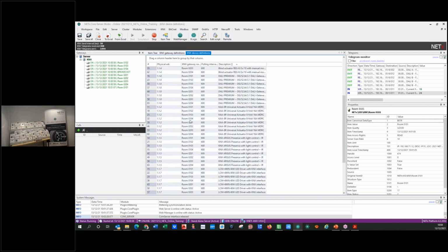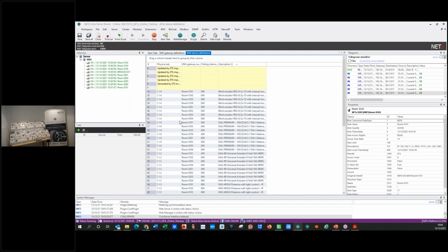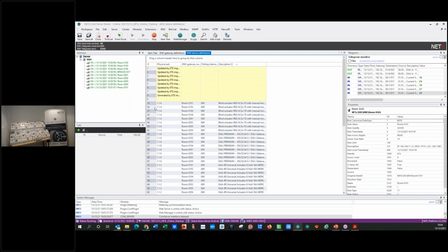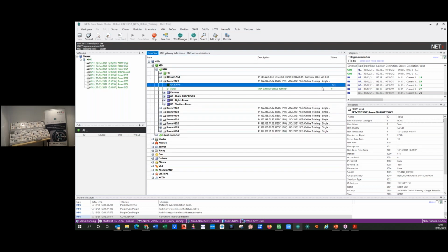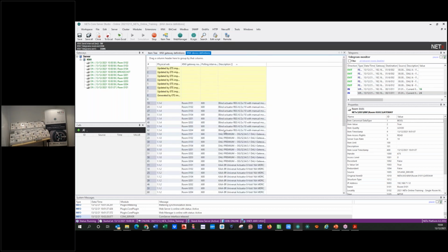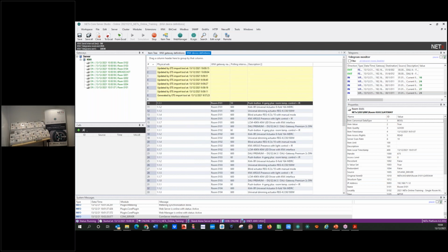If you look here, the 116, that is the IP interface, is not present because you are monitoring the IP interfaces in a different way. We are monitoring as a gateway. The gateway is here, so it's not necessary to monitor it again as a device because it's a gateway itself. But these are intelligent decisions from the BMS that are maybe sometimes hidden or invisible for us, but very important, because if not, something not good can happen if you do this monitoring in parallel or whatever. But the BMS is very intelligent in this way, because behind the BMS are very intelligent people, my colleagues. Hello to all of you.